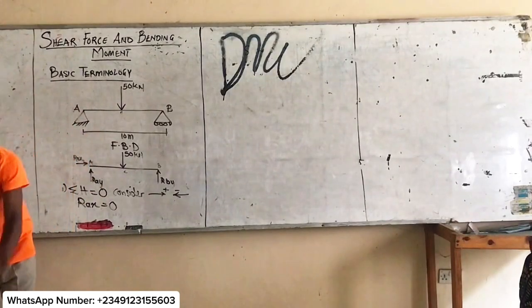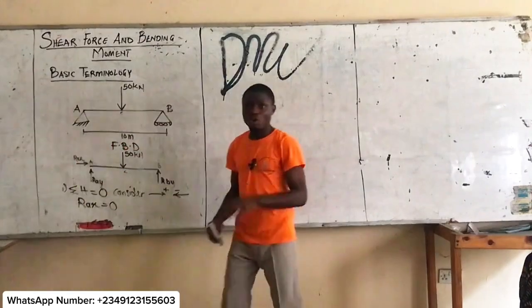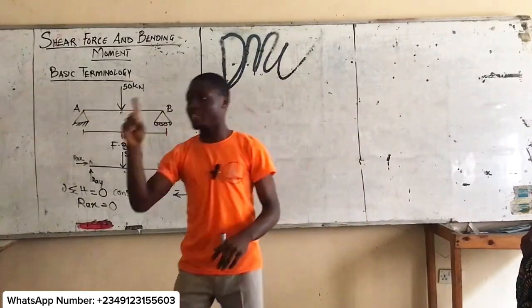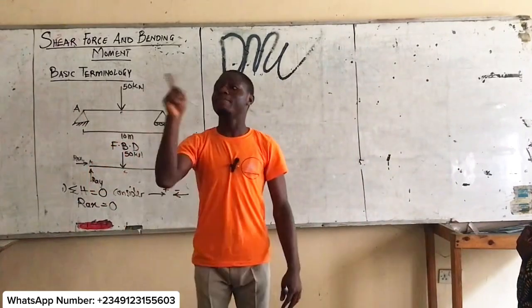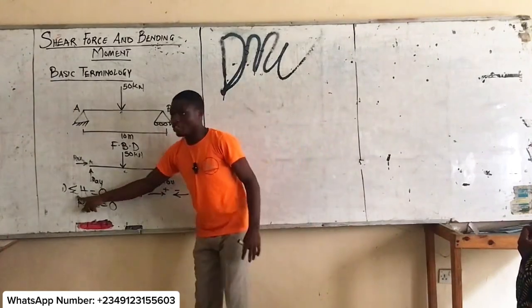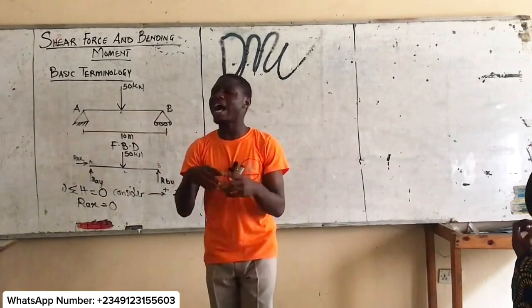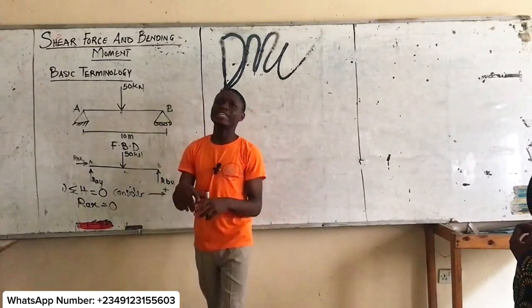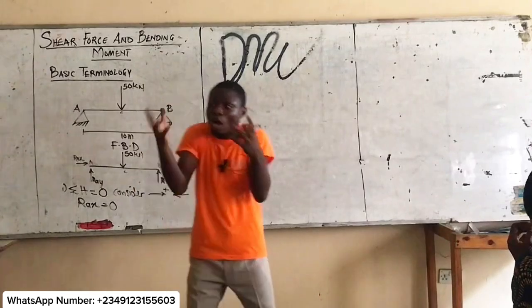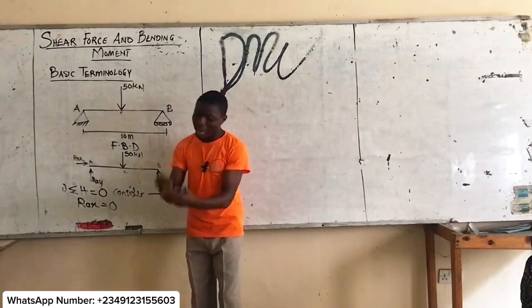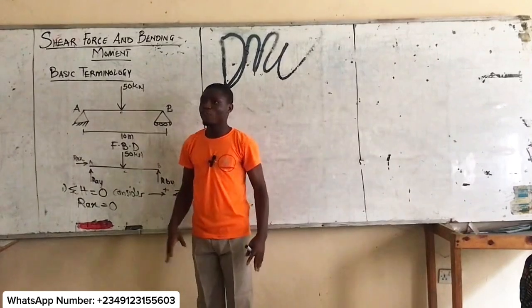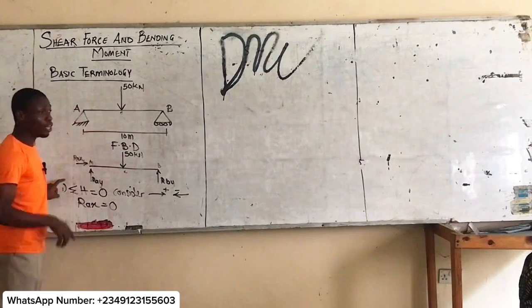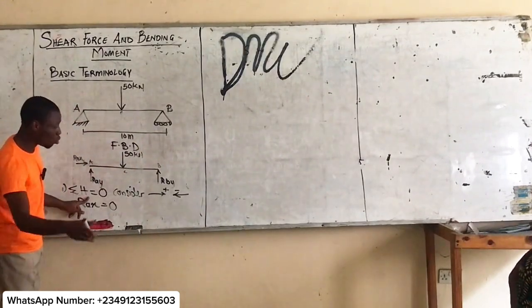Basically, for strength of materials, we don't always consider the first condition of equilibrium because we know it ends up as 0. Listen, in strength of materials and applied mechanics, they are both similar. When it comes to applied mechanics, you must always do summation H, but in strength of materials, at the end of the day you end up adding zero. So I can ignore calculating summation H. But for now, let's start by considering it. That is the first law of equilibrium: summation H equals zero.